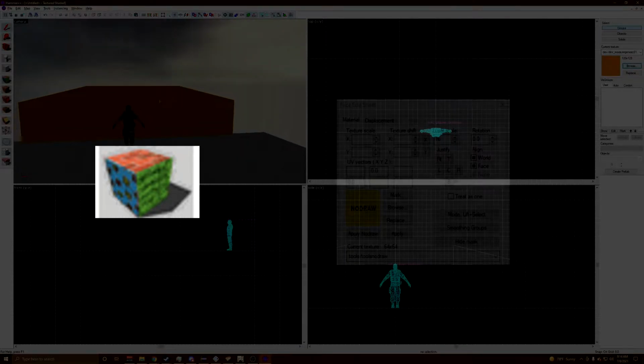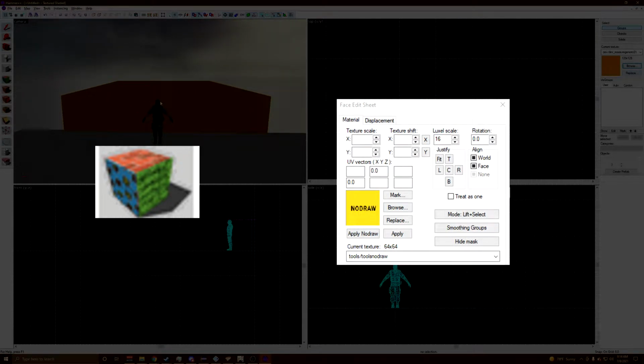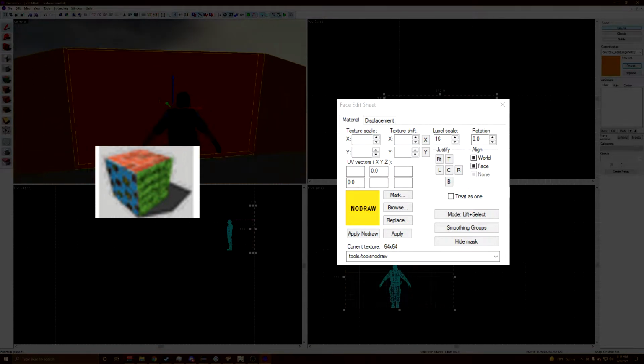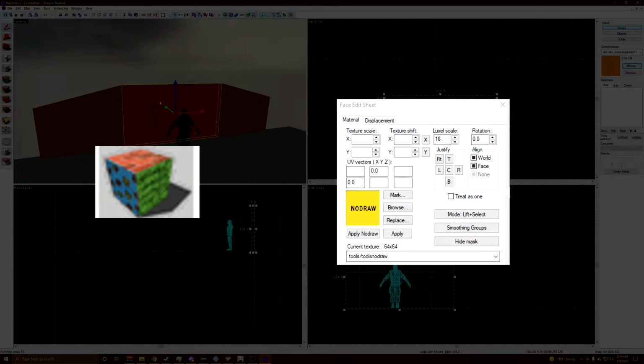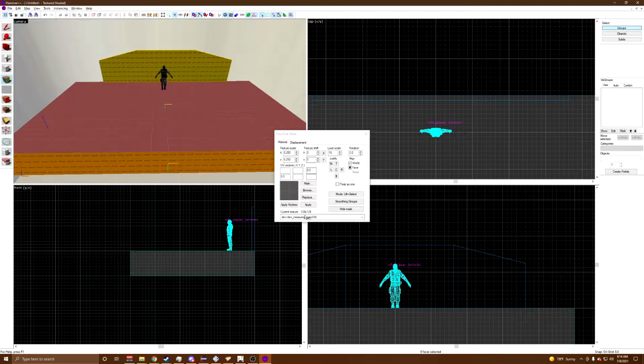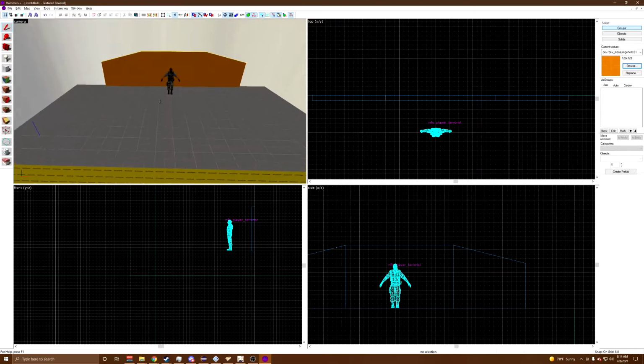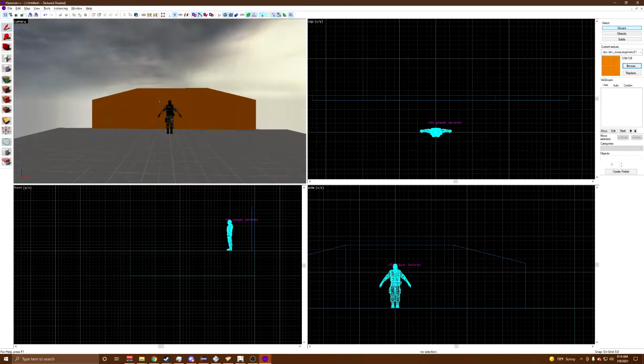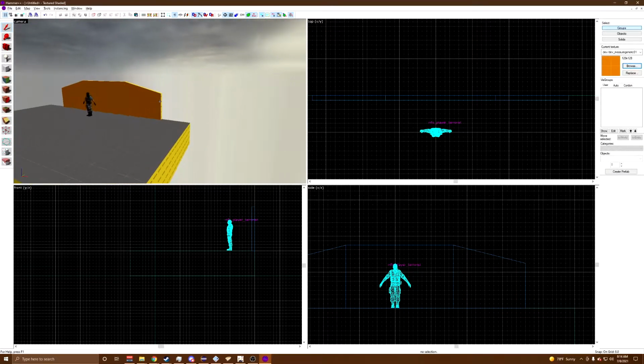It will open up a prompt where if you left click on a brush face, it will adopt the texture that is currently applied to it, and if you right click on another face, it will apply that texture onto that brush face. Additionally, you can select other textures from the texture search menu like we did earlier, but I already grabbed our dev textures from earlier, so I'm just going to select them from the drop down. Also, don't worry if anywhere my UI looks different from yours. Those are just some changes made by Hammer++.